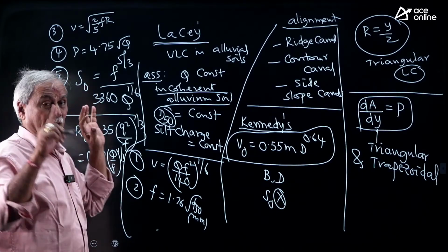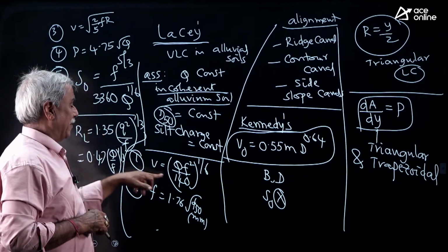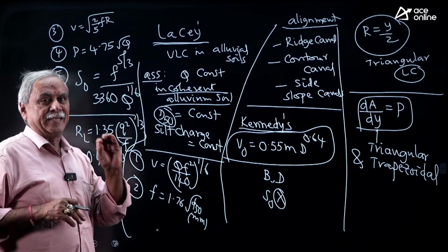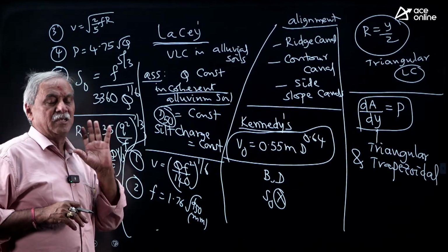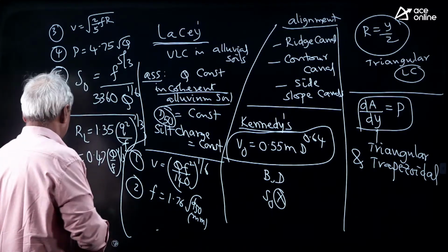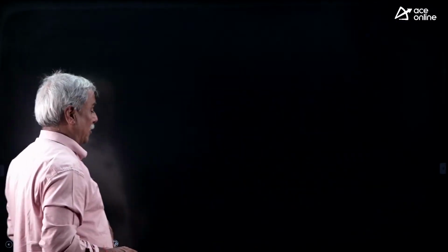Lacey's formulas have only one drawback. Everywhere F will be required. So if you take proper precaution for F, the design details and outputs given by Lacey's theory are very, very accurate. And then we see the canal regulation works,